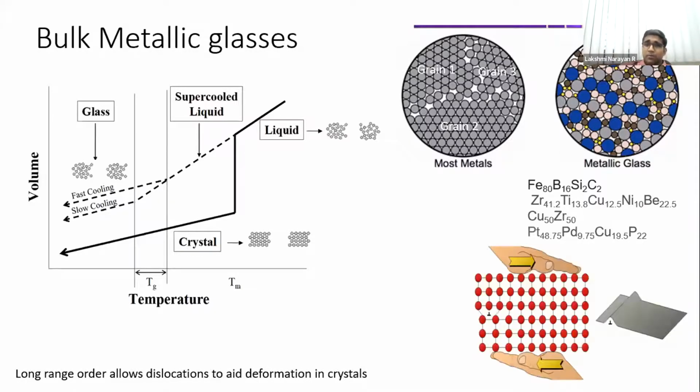Okay, and the problem with that, or I would not say problem, the only difference is that in crystalline materials, deformation is modeled via dislocations, and dislocations are essentially moving in a crystal which has a very well defined crystallography. So you can define a dislocation, you can understand how deformation takes place, but metallic glasses cannot have dislocations in such a simple sense. Of course, a lot of people have worked on some of these ideas, but they only came up with approximate models. Disclinations is one model, but of course very difficult for mainstream metallurgists.